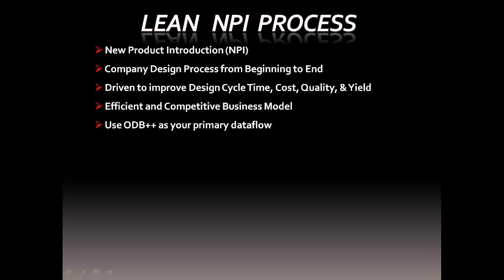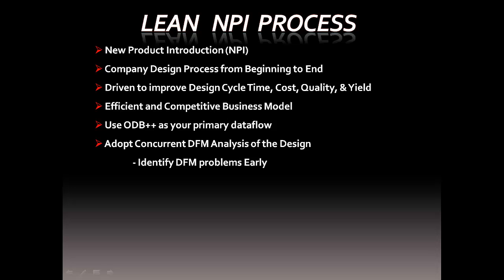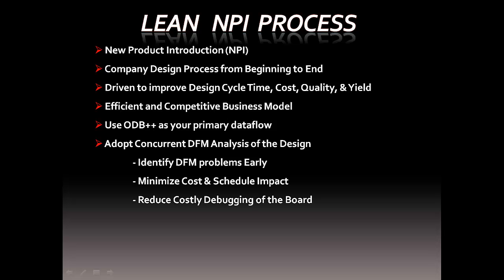We have adapted to concurrent design of the schematic and PCB layout, and now we must learn to adopt concurrent DFM analysis of the design. Applying the left shift method to your DFM practices will greatly improve your time, cost, quality, and yield. By left shifting, you identify DFM problems early in the design process where their impact to cost and schedule are minimized. It's extremely difficult and time-consuming to make changes at the completion of the PCB layout or to spend costly hours debugging the board on the benchtop.